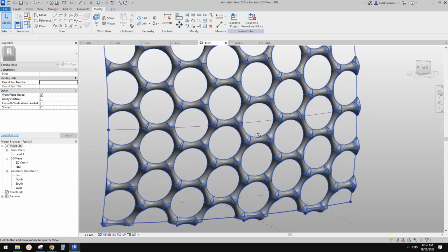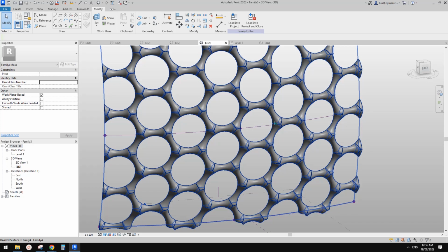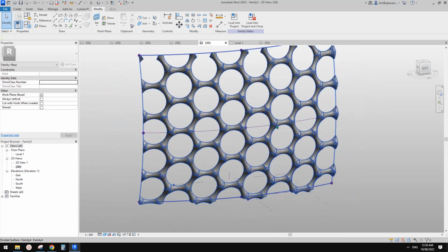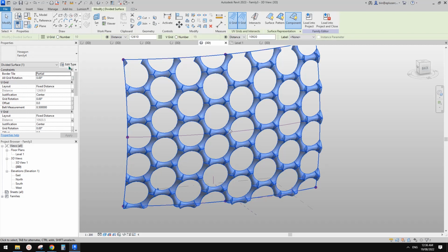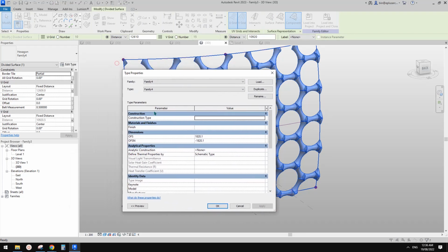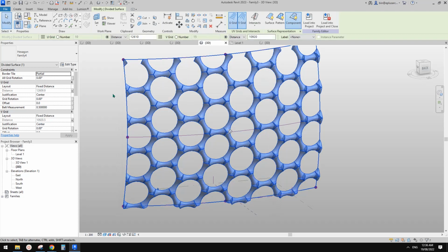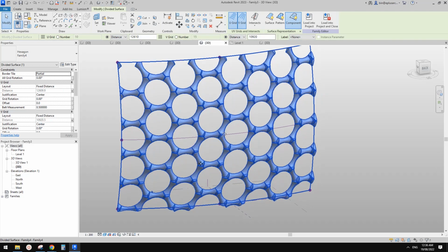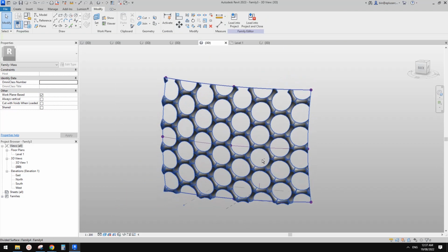I'm not 100% sure, but it's possible we uncheck the shared parameter and then delete this pattern-based family in here, and then reload that pattern-based family, so we can somehow build that link from the offset to this X and Y. So every time we change the pattern or the grid, we don't need to adjust the offset to be 1/6 of X. Other than that, it's all good.